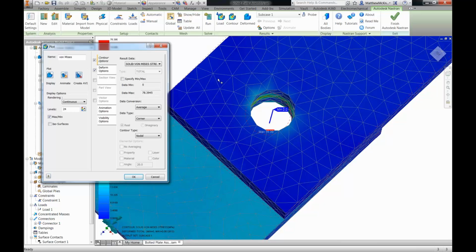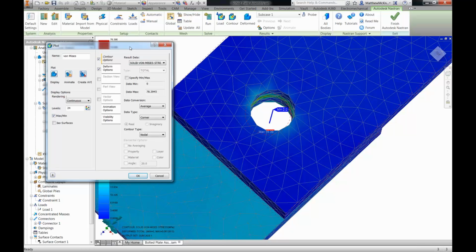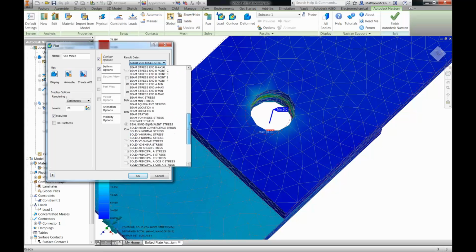So recognize that if you are getting very, very high loads that you are concerned about in these areas, then looking at those loads and stresses in that area needs to be done in a different format, potentially using actual 3D geometry to understand what's going on. Beyond that though, you can see that we can look at things like stresses. We can look at beam and bar stresses throughout our part.